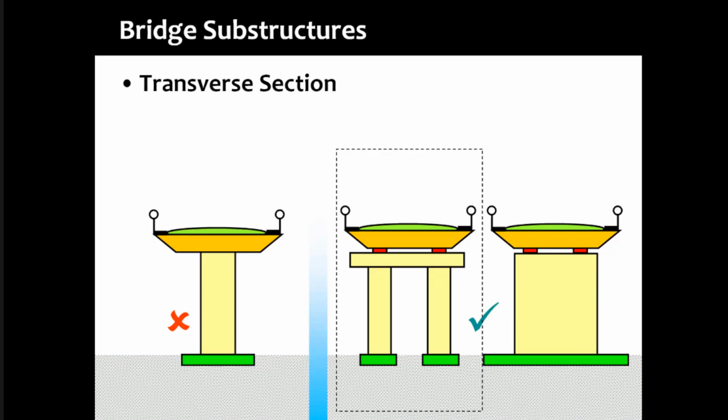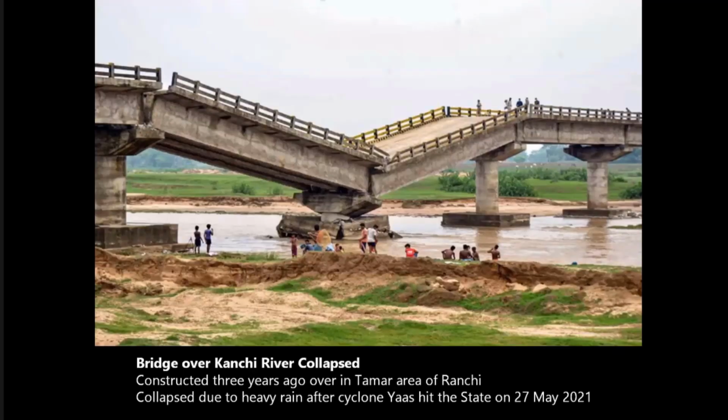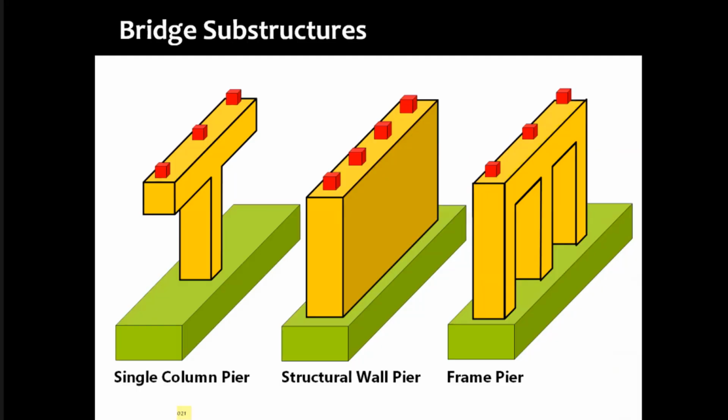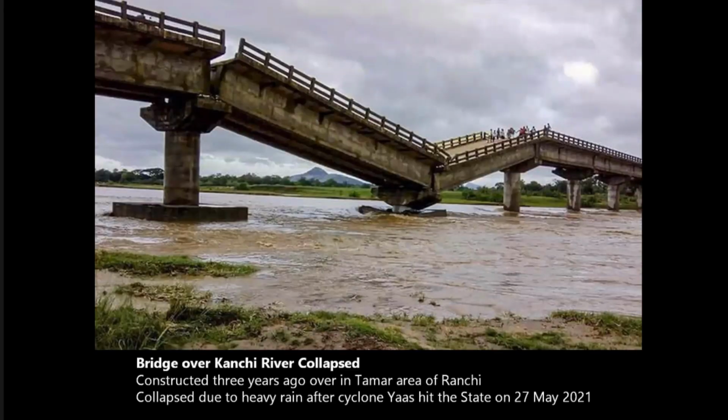So our choices are between a twin column, twin pier frame pier, or a wall pier. Just to show you that we don't need earthquake shaking, even otherwise the substructures are not being attended to carefully, and so we are having damages and collapses in bridges, right? So this is something I want you to remember, that we have not been paying attention to bridge design, especially the vertical member. The horizontal is not at all in any trouble. You can see this, it's spick and span. It's so stiff, nothing can happen to it.